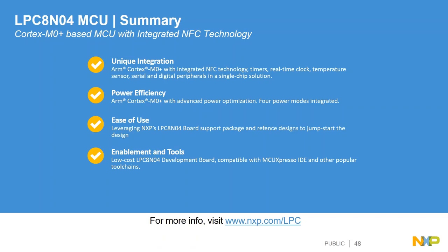We are able to do energy harvesting thanks to this power efficiency. So we're able to power up the device without the necessity of having a coin cell battery or having a USB attached to it. That's also a big plus because of the power efficiency features available in the LPC804. And as I have mentioned in these last slides, the ease of using the enablement and tools. We have board support packages. We have reference designs to start the design right away.